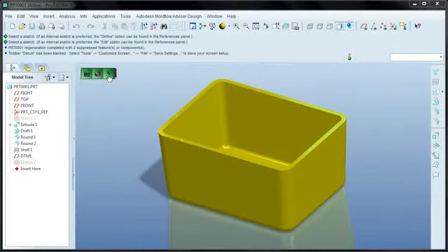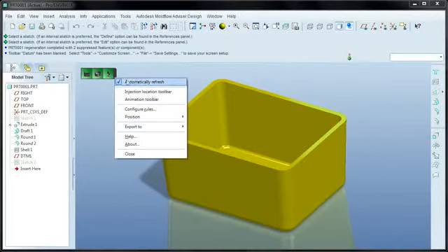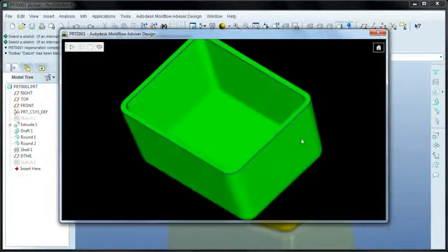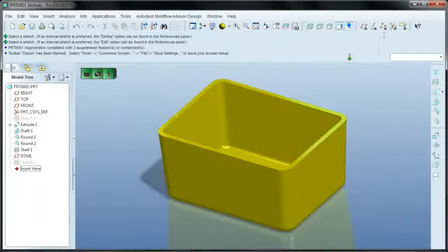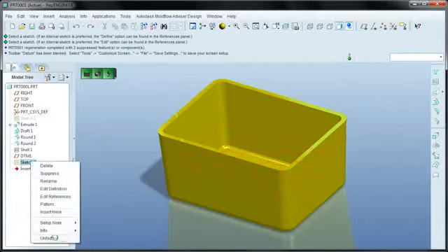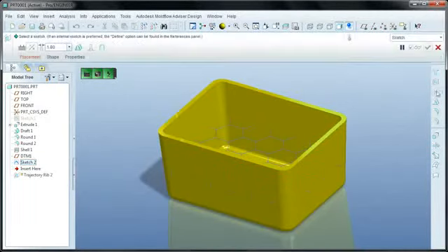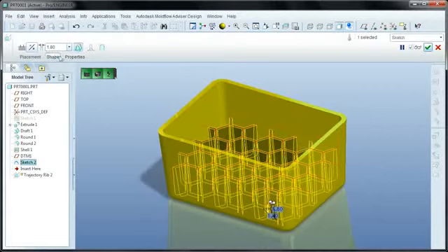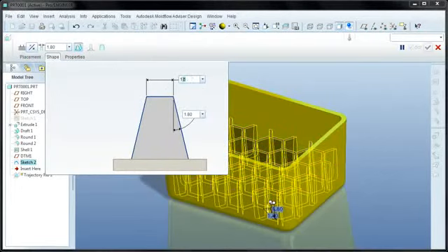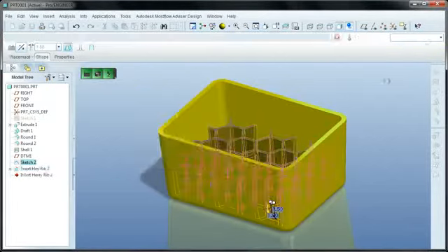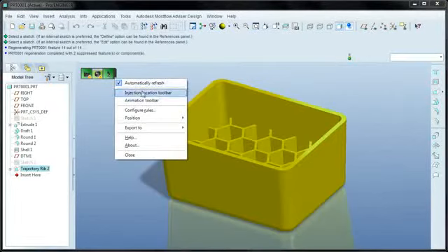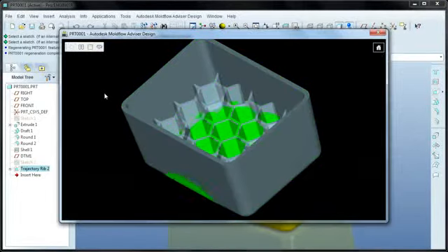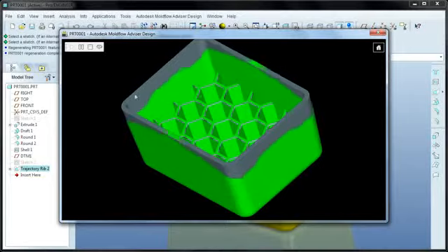The non-intrusive icons in the viewer give you easy to interpret information about the manufacturability, cost, and environmental impact of your design. We'll start by pulling up the fill preview. This shows an animation of how the plastic is going to flow through the part so you can ensure it will fill completely and evenly. The amazing thing, however, is that the fill preview updates after every design change you make. Even when adding a complex feature to the part, the filling pattern updates instantaneously, giving you the ability to evaluate the impact of every decision you make as you make it.